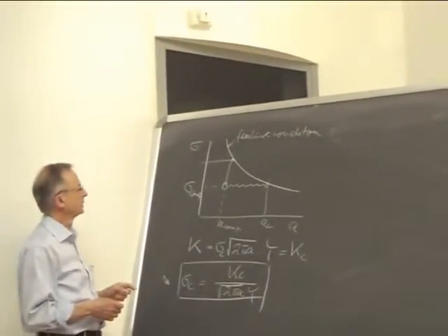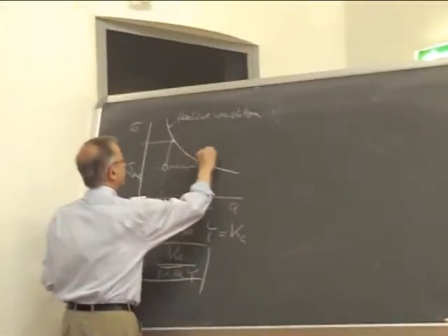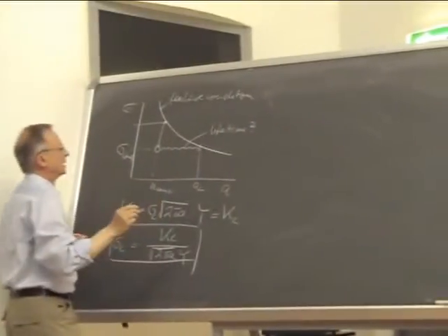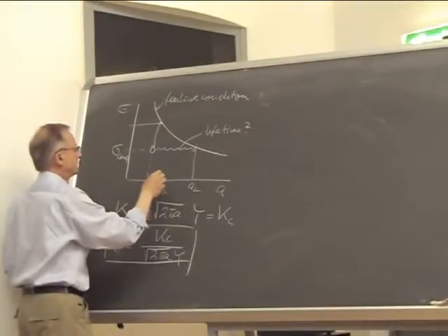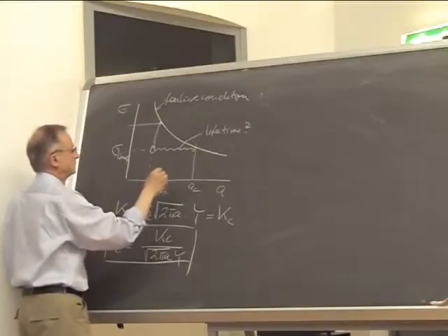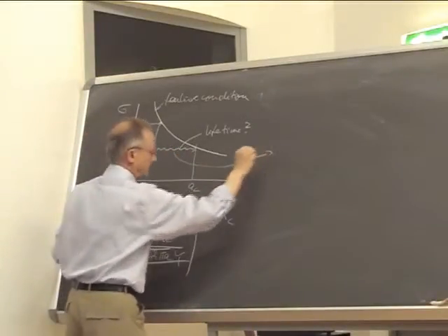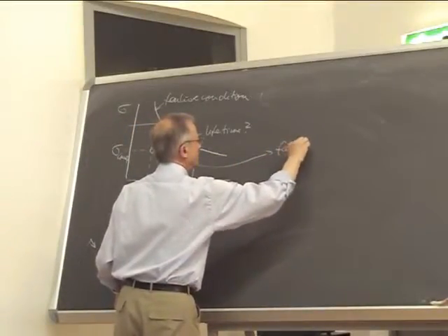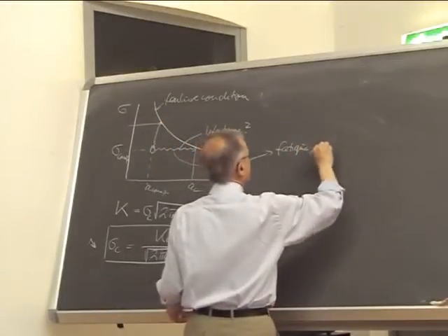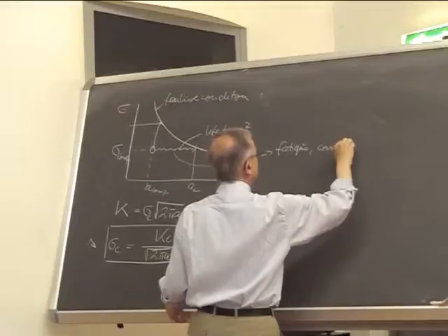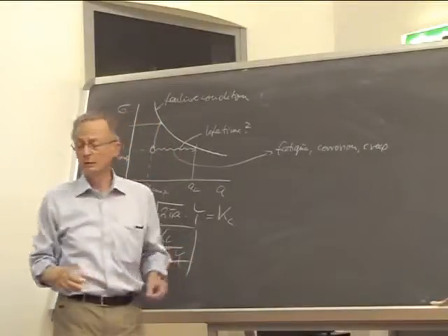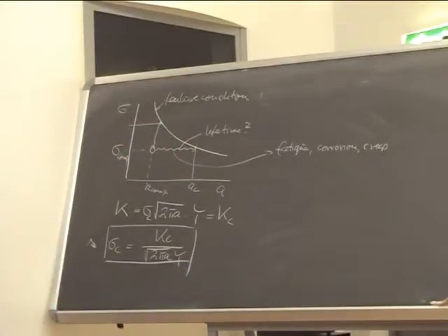The crack can, now it's going to be messy now, lifetime, in quotation marks, the crack extends by, not a reference line here, by fatigue, corrosion, and/or creep, high temperatures in aero engines for example, or a combination of all three nasty things.